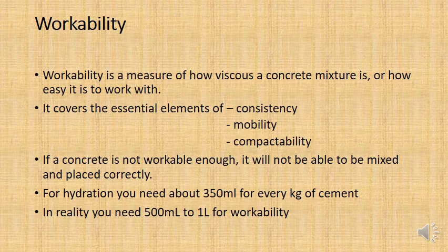Those are the properties of workability. That's why we need the concrete to be workable. If the concrete is not workable enough, that will mean that it has very high viscosity. It'll be very thick, and that'll mean you won't be able to mix it properly. And it also means you won't be able to place it properly.